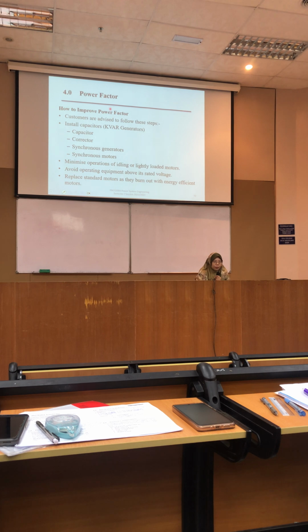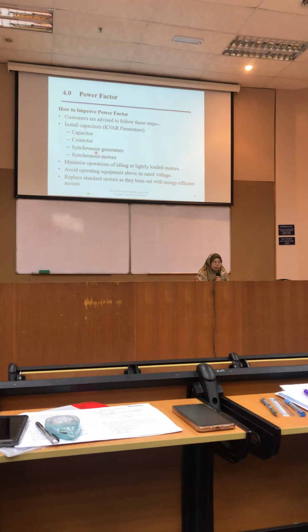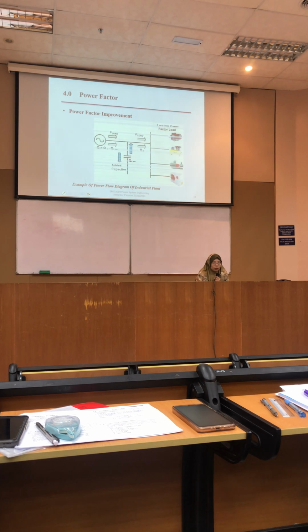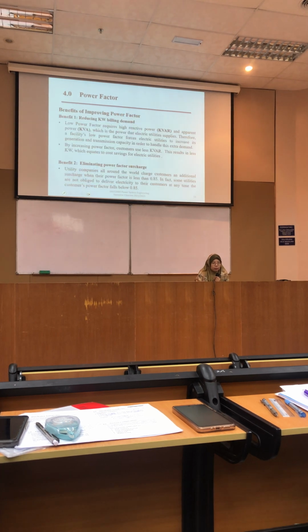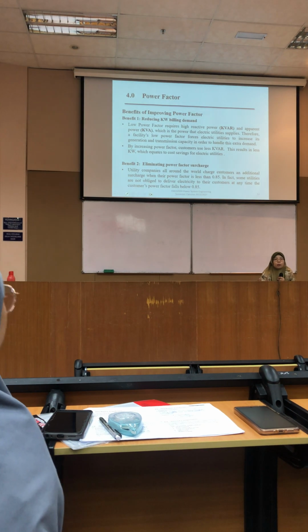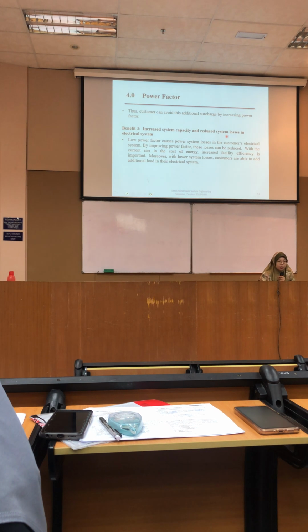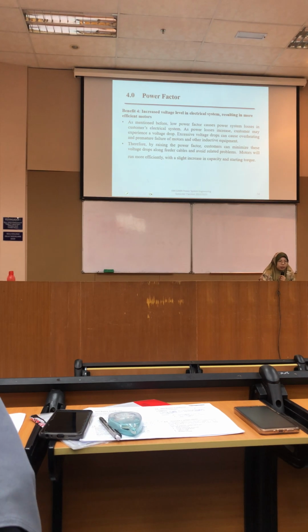So how do we improve the power factor? Capacitor bank, power factor corrector, synchronous generator, synchronous motor. With this we can reduce the electricity bill and eliminate the power factor surcharge, because you are paying for nothing when you have the surcharge. It also increases system capacity, reduces system losses, increases voltage level, resulting in more efficient motors.